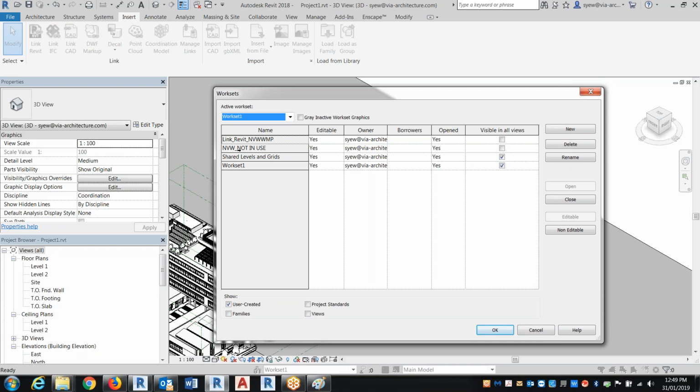So if I want to grab your structural drawings and then turn off everything else, then just tell them that this is what I'm going to do. Make sure you have the same name, a consistent name, and don't change anything. Once they understand how things are done, next time when they receive your file, tell them that this is what I'm going to do. If this is important to you, then just put it inside that workset, and then when they receive it, it becomes consistent all over the place. So you do not have to deal with, oh, what's missing in their workset.